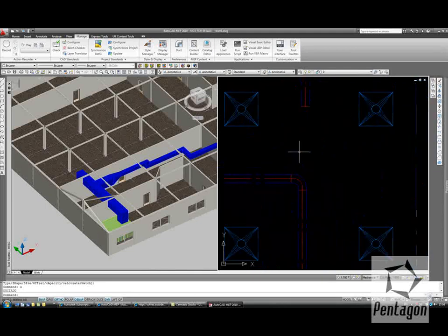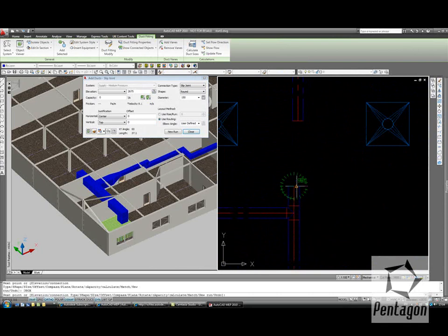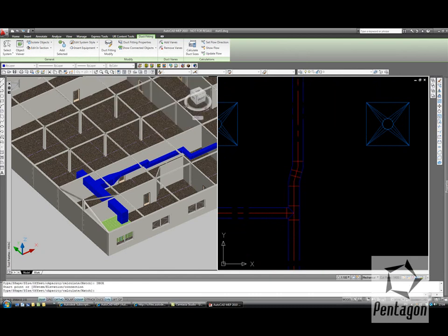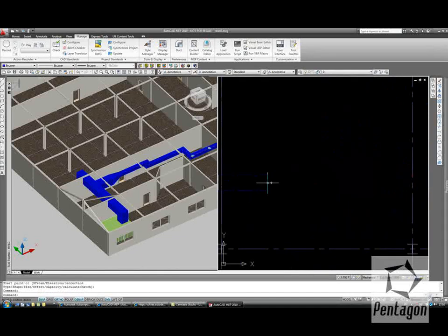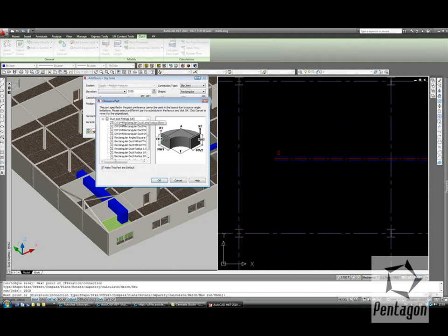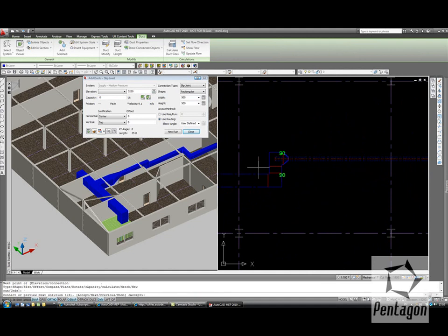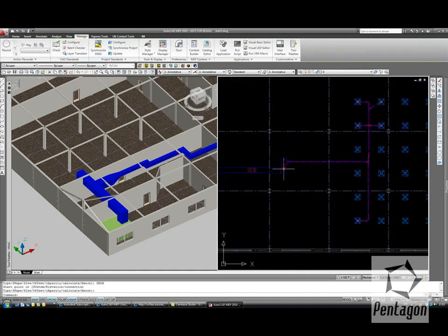So I have two ducts not quite lined up. Again, we can take off in here, and we can automatically connect to this duct using our snap transition tools. Again, you can see that it's actually adjusted to make an angle to make these ducts actually connect in here. So with great flexibility in AutoCAD MEP, I can very easily connect various ducts and systems, and it'll prompt for the actual transitions or T's that need to be added in. Even if there's a custom layout to be made, AutoCAD MEP will automatically generate it.